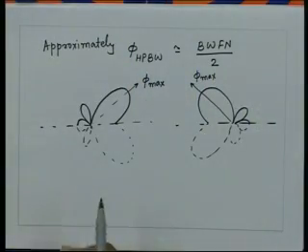However, if we make an approximation that nulls are equispaced in phi, then we can find the direction of the maximum radiation and the null, which is half of the beam width between the first nulls, which is approximately equal to the half power beam width of the array.